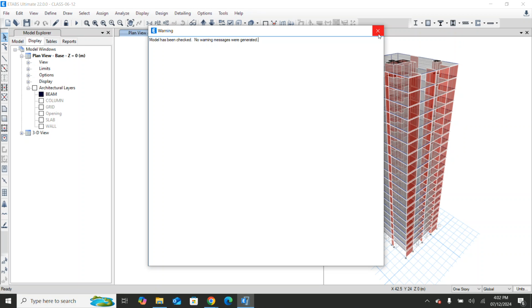So in that case, if you did not follow everything over there properly, many issues will show up. Basically, model-related problems can be intersections, clashes, or the same element coming more than one time in the same place, like two or three section properties assigned, or a wall, whatever. Anyway, first we have to check that the bottom one is properly done. If there are any issues, then only you have to go to the other one. If you want, I'll show you.